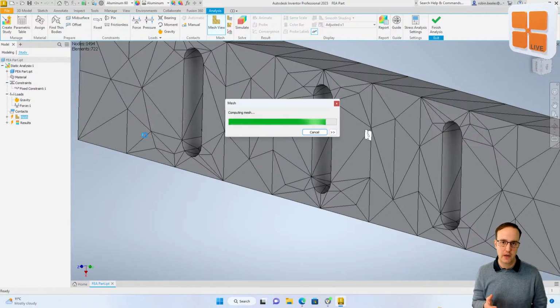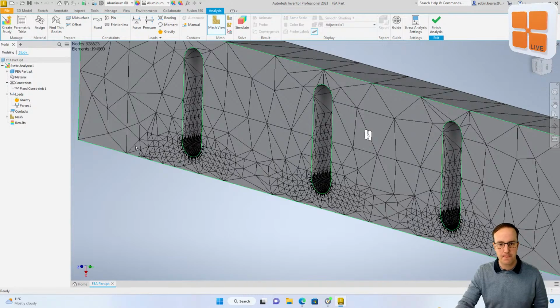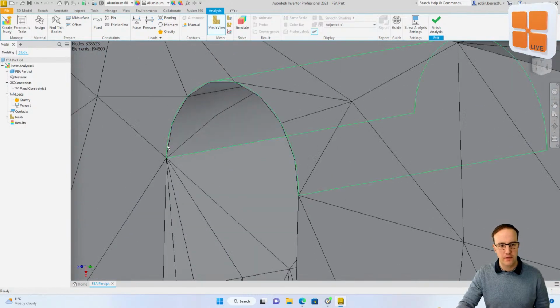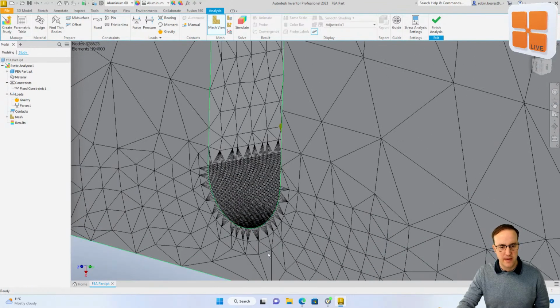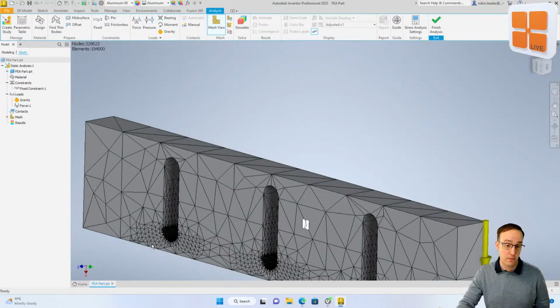So there are many more triangles. Because there are more triangles and the triangles are smaller, each section of result within those triangles is going to be of greater accuracy. So the more refined your mesh, the better accuracy you have to the actual shape. Therefore, the better results you have. If you, for example, compare the shape on the mesh, ignore the green edge, look at the shape of the mesh. It's faceted. If we look at the bottom and look at the shape of the mesh, it's far more refined. Your simulation will take a much longer time to run, naturally.